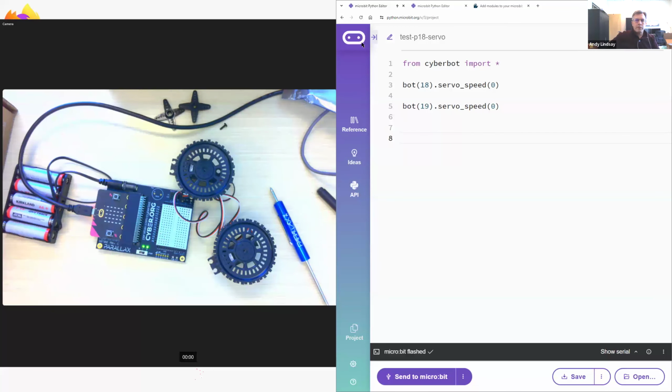While I'm waiting for a few more thumbs up to come through, I'm going to modify this script. We'll go 65 in the counterclockwise direction and then negative 65 for the clockwise direction. So after you've got your servos centered, I'll add a comment here.